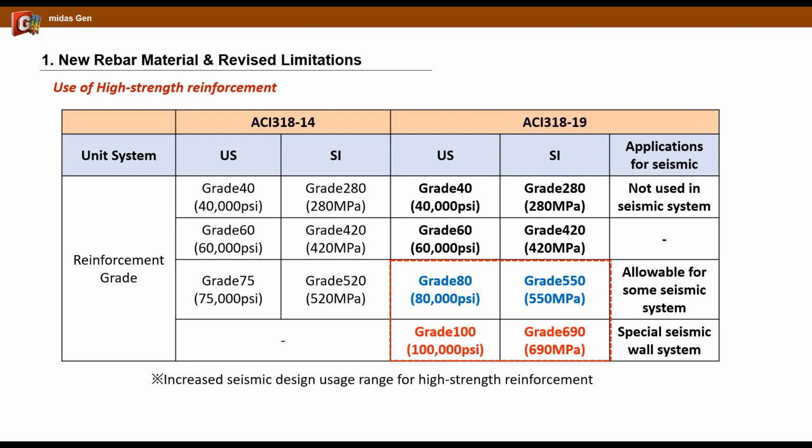Strength and ductility concerns were addressed by introducing new requirements for mechanical properties of reinforcing bars, adjusting the method for calculating the strength reduction factor for moment and combined moment and axial load, revising development length provisions, and limiting the value of Fy that can be used for calculating the maximum axial compressive strength (Pn)max of columns. It is likely that grade 690 reinforcement will be used mostly for vertical bars of shear walls and columns, though it might also be used for heavily loaded floor systems.